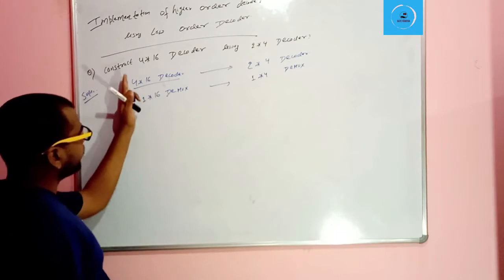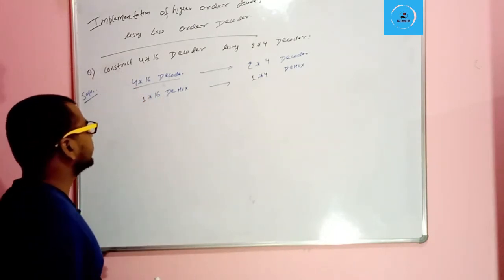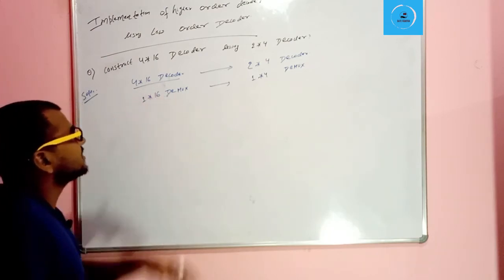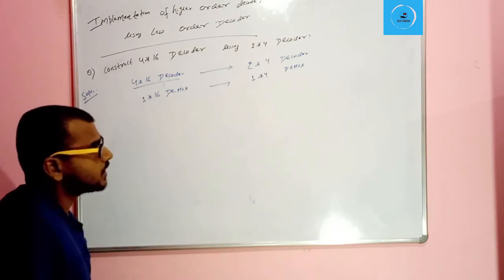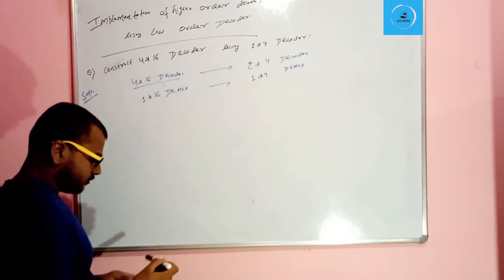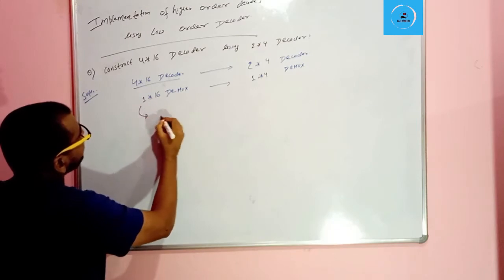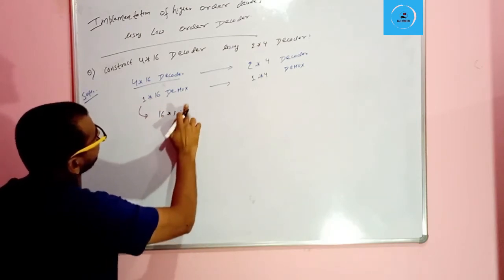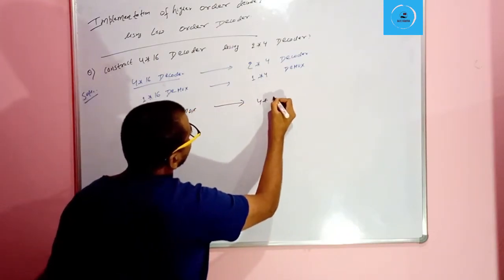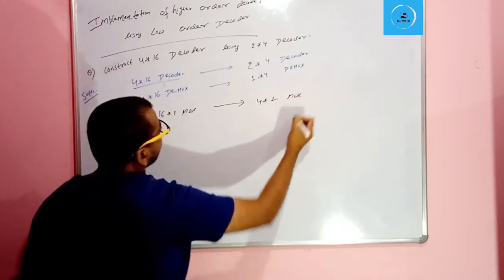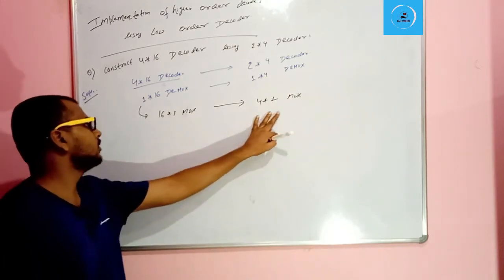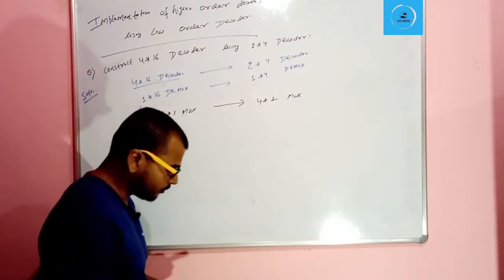Observe here, the 1:16 demux we can also say as a 16:1 multiplexer, and the 1:4 demux as a 4:1 multiplexer, and we are good enough to solve how we can construct the 16:1 multiplexer using the 4:1 multiplexer.